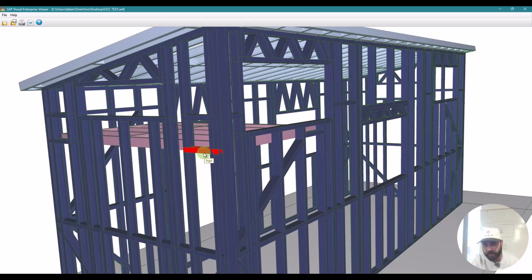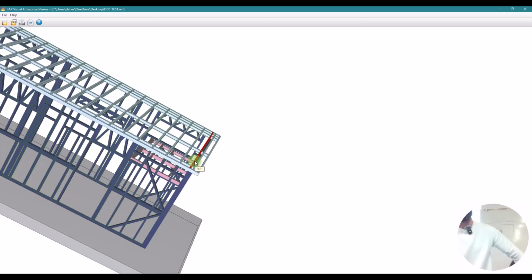if this window was too close? We need at least 9 inches, so if I knew that this was closer than 9 inches, well, maybe I restack the order of the end wall and the side wall to be able to drill it from this side, because you have 16 inches on this other elevation. We've never done something that we put together, and after we put it together, we haven't gone back and made one tweak to make it better.